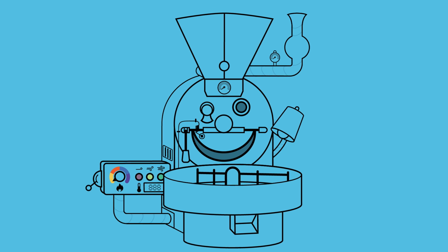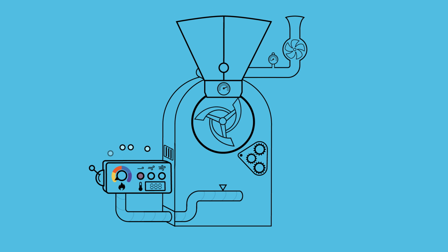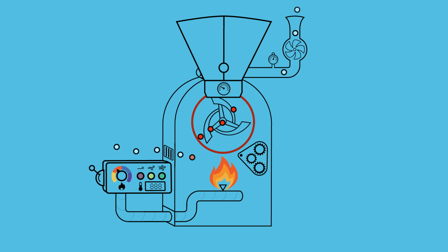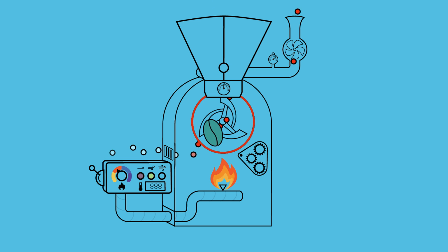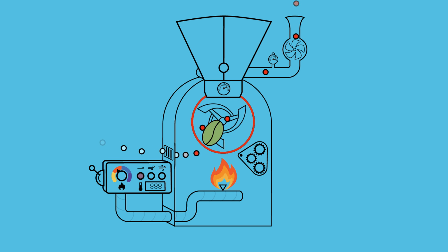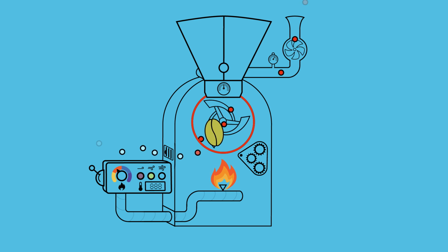Fundamentally, the roasting machine is a convection oven. It is a mechanism for inflicting heat, energy, onto whatever it is that you're cooking. In this case, we're cooking coffee. It's a convection oven that generally is in rotation and that is moving the coffee, transferring heat through a few different methods. Let's get nerdy about heat.